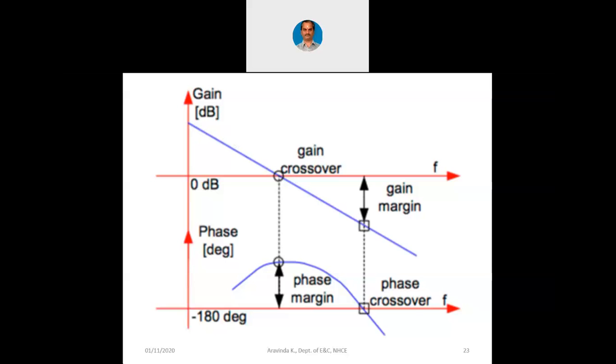deteriorates. So in such a case, when the gain keeps reducing, a point will come where at a particular high frequency gain will become 0 decibels, which means as output is falling down, at one particular frequency output will be equal to input. That means the amplifier will not be working like an amplifier. Now at the same time, as the phase also is going to deteriorate, 180-degree phase shift may not remain even at higher frequencies, and the phase will keep changing.